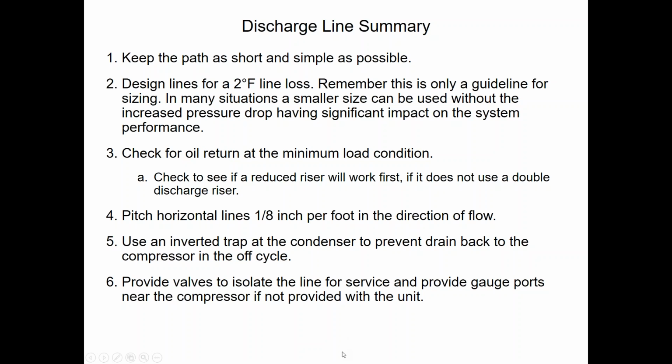Hey, I'm a service guy, so I love isolation valves. I like the isolation bypass valve around filter dryers. I like isolation valves at the condensing units, the condensers, the chillers, which many of our pieces of equipment already have standard. But always think about that for service down the road.